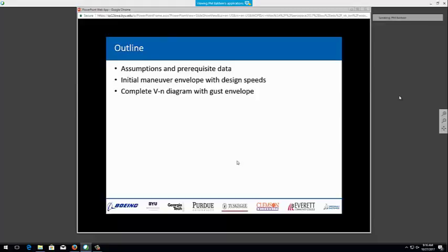Then there's the structural maximum dive speed. This is determined typically with aircraft, and it could be for yours too, by the flutter speed of your wing. We have some pretty flexible structures sometimes. Sometimes we have carbon fiber foam wings that are very, very rigid. Other times the balsa Mylar is not so rigid, and we can get into flutter problems at high speed.